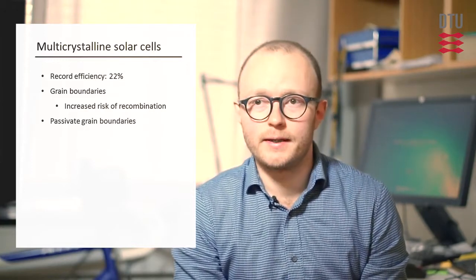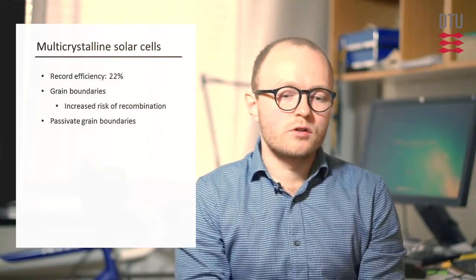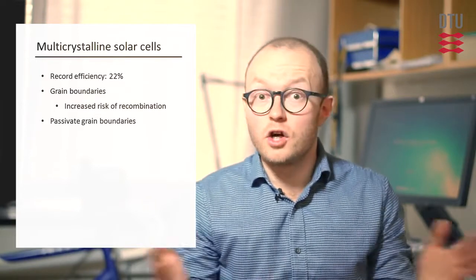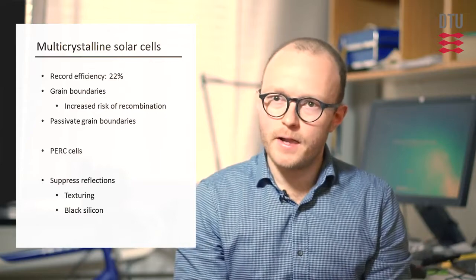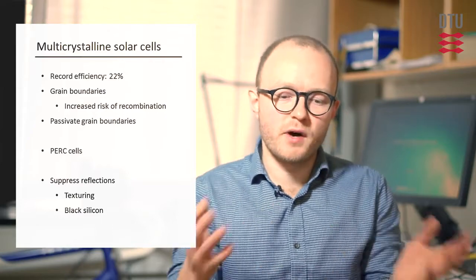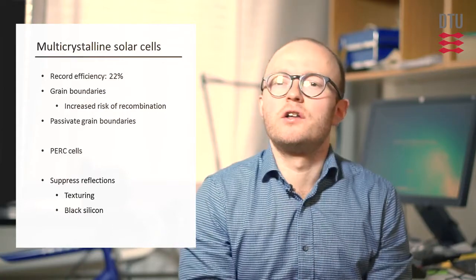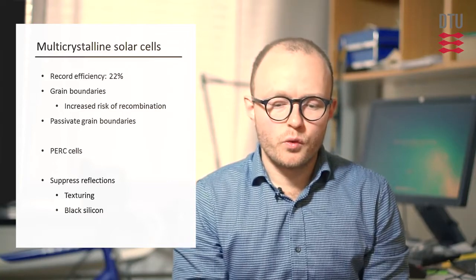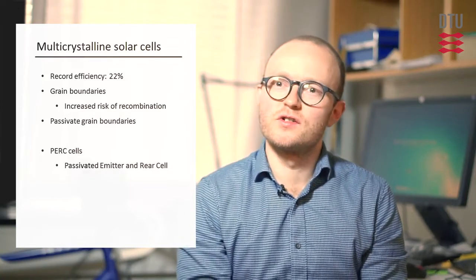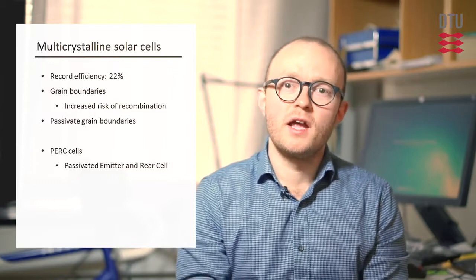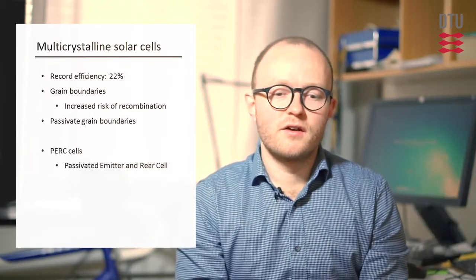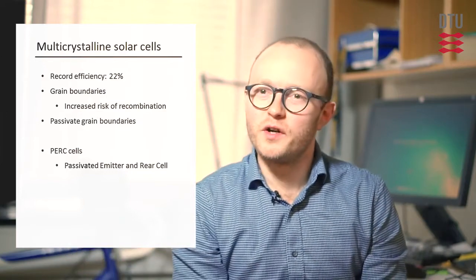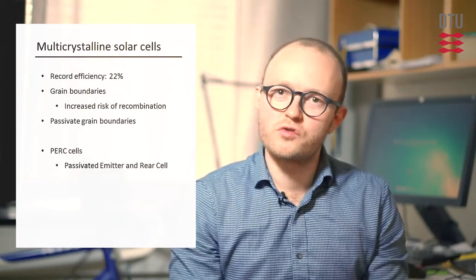So that's very important. A lot of work is also being put into, even at industrial scale, making what's called PERC cells. And this is inspired by the PERC and PERL technologies, where you passivate the surfaces also on the rear and make local contacts instead of putting a metal on the whole rear, which is the industrial standard.